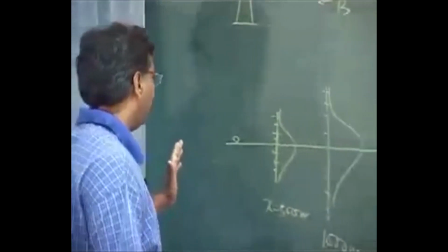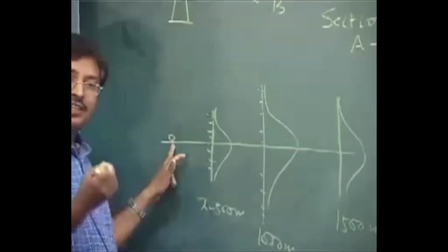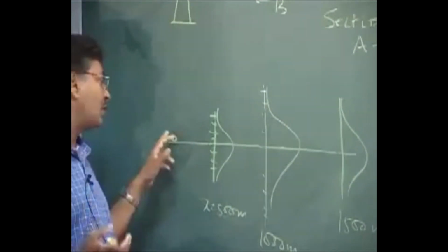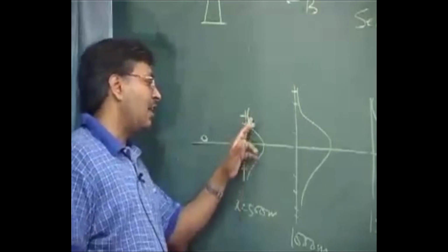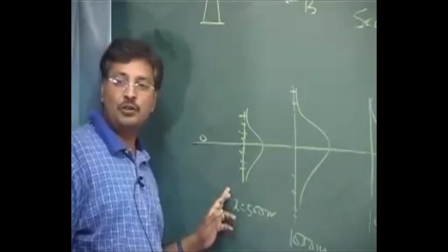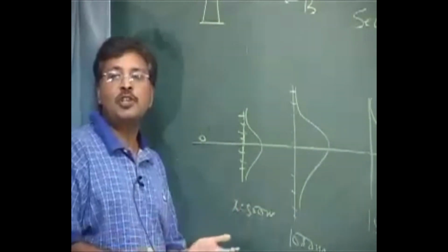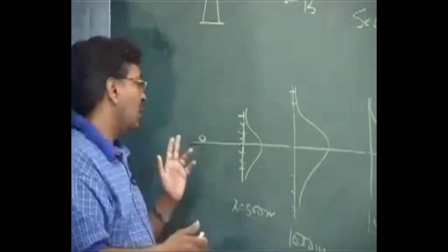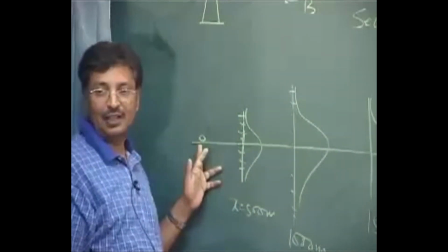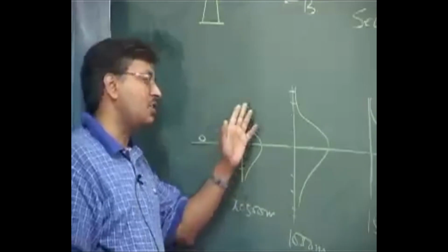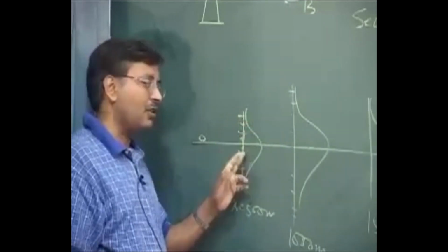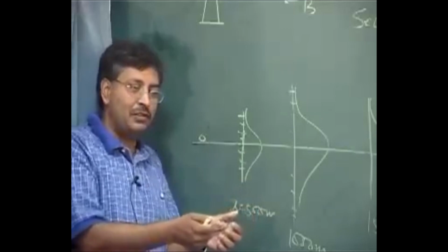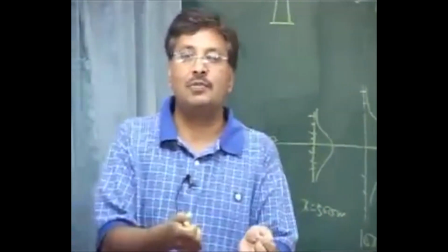So what they did was run this experiment by releasing some tracer. Suppose you are working with sulfur dioxide; it will always be in this area from some other source, and the results will be a mixture of sulfur dioxide from various sources. So they release some tracer that is not there in the atmosphere, so they can measure accurately. They go to the fields with some small handy gas chromatograph or whatever instrument, and they measured at different places of y, at the same time.